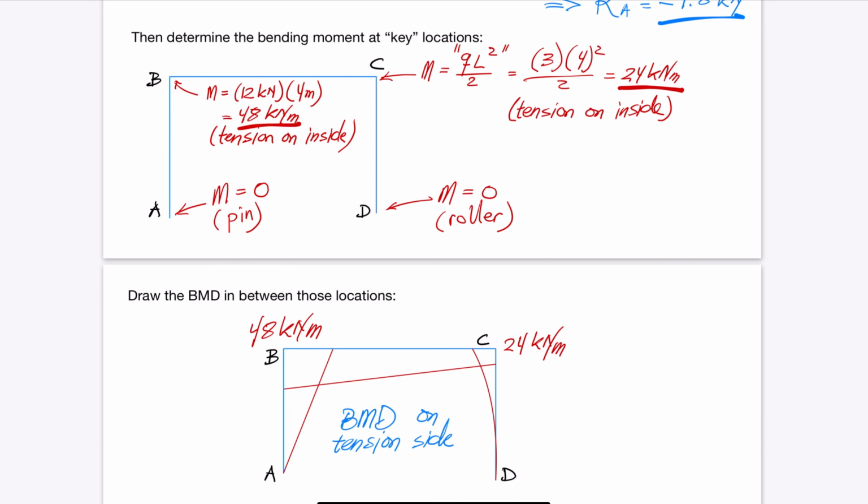Do you see how the horizontal leftwards acting force equal to 12 kN gives tension on the right-hand side of the column at point B? If not, hold your plastic ruler vertically to mimic this column, apply the force, and feel with your hand which side is in tension. This is an important exercise that builds intuition and experience with which side is in tension. Remember, we draw all bending moment diagrams on the tension side.